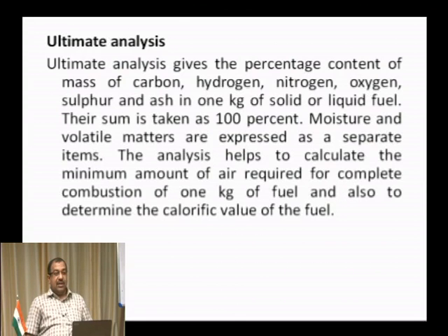Okay. They are completely separated out of the percentage of the mass of the particular composition of the fuel. The analysis helps to calculate the minimum amount of air required for complete combustion of 1 kg of fuel and also to determine the calorific value of fuel. If this analysis had not been there, then it would have been very difficult to analyze the given fuel, because we would not be sure what is the total amount of heat it is going to produce. For the determination of the calorific value, this analysis is very important.